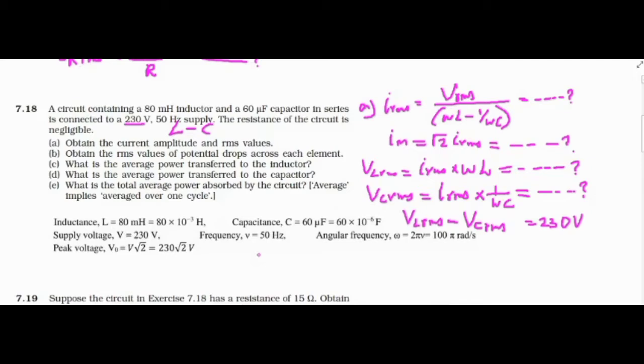The reason we have seen in question 11. VL and VC are in the opposite direction. So here the applied voltage is the difference between the voltage in the inductor and capacitor, just like the difference we have taken in the phasor diagram of the LCR circuit. Remember, we have taken VL minus VC.